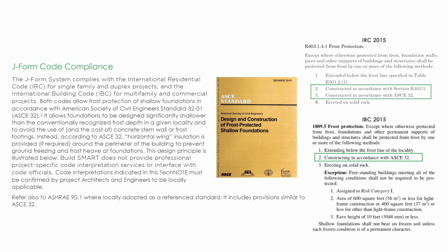So we've been talking about this ASCE 32, and the ASCE 32 is pretty lengthy. It's got a lot of jargon in there with regards to how this operates. So insulation is provided to retard frost penetration below the foundation and to retard heat flow from beneath the foundation, allowing shallower footing depths to be possible with no added risk of frost damage. That's basically what this intent is.